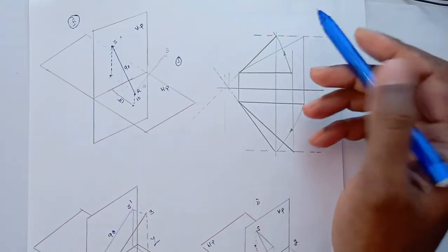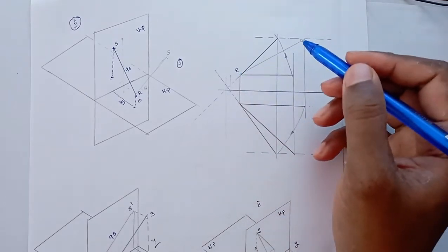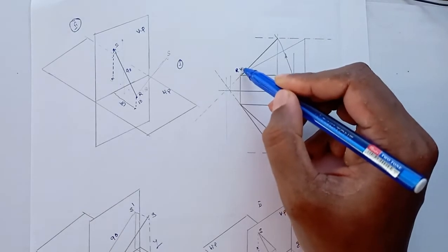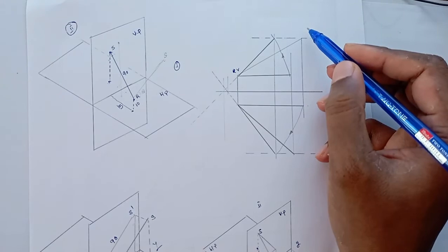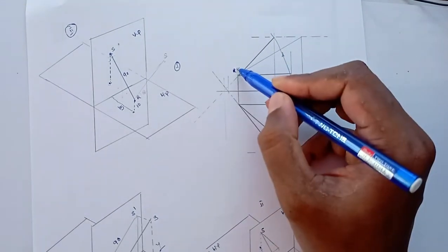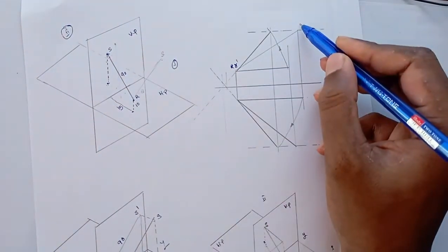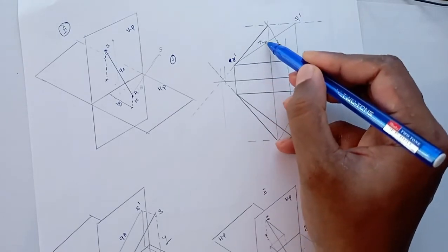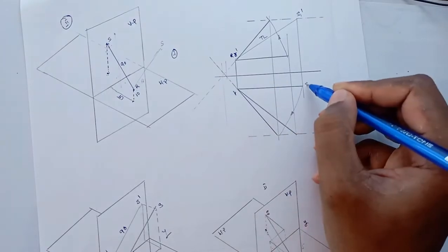Okay, understand the basic figure first. This is our basic figure of line rotation. Suppose this is our point R. The first procedure is to make the line parallel to VP and draw the front and top view by keeping one point and rotating the other. I am keeping my point R constant, and this is R dash, and this will be S1 dash, and this is our true length. And it gets a front and top view. The top view is R, and the top view will be S1.